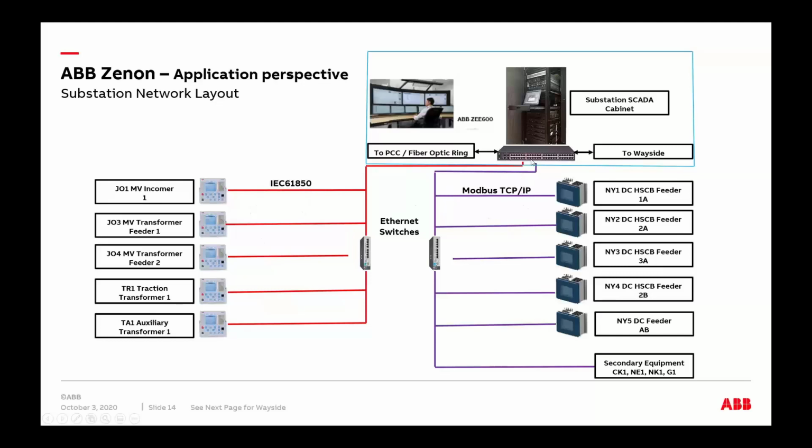So I could bring that to my Ethernet switch. Remember, this is my smart Ethernet switch. Both sides, both networks, depending on what protocol they are using, and you will be monitoring that system either at the level of the substation. You could build for them maybe this type of a rack, or maybe then you need to move that information to an ACC room, or maybe there is a control room not far from the substation. So that's typically how you do it.